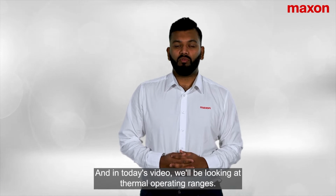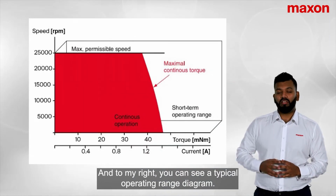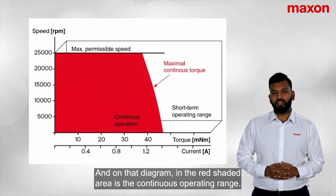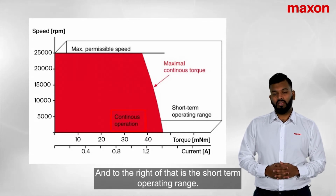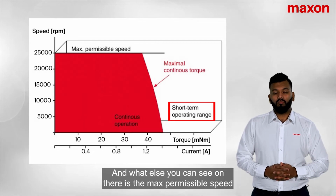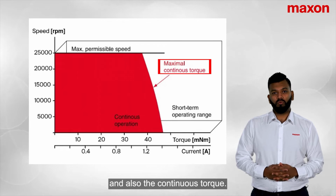And in today's video, we'll be looking at thermal operating ranges. And to my right, you can see a typical operating range diagram. And on that diagram, in the red shaded area, is the continuous operating range. And to the right of that is the short-term operating range. And what else you can see on there is the max permissible speed and also the continuous torque.